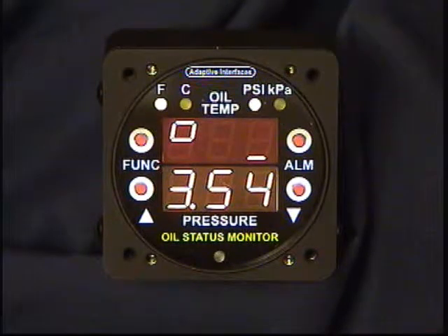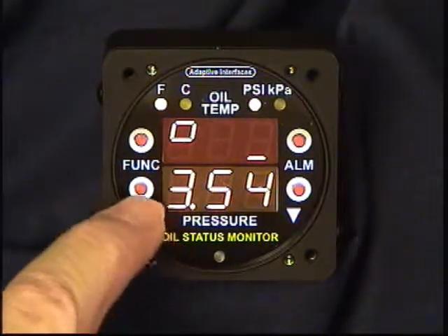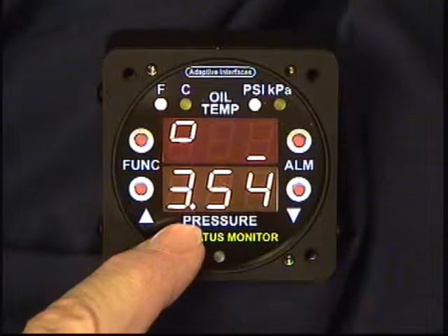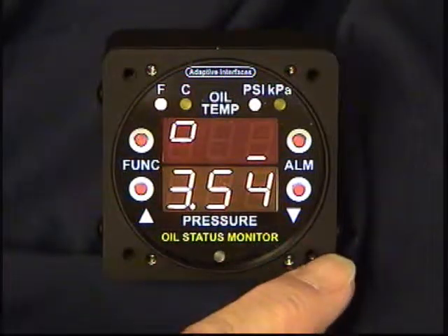Again, for each sensor, for a temperature sensor, you have to have 2 data points. One is the value of the sensor and the temperature associated with that value. And so right now, because we're using a resistive type temperature sensor, the value is the resistance of the sensor in ohms.